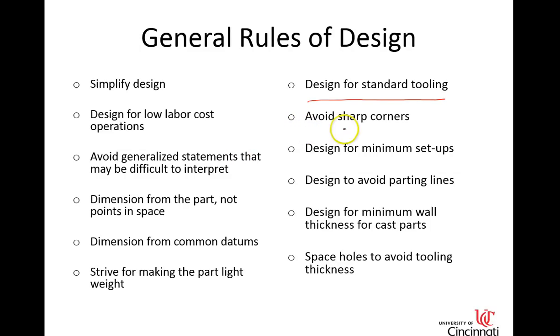Avoid sharp corners. Stress risers are one reason. Another one is they're not always that easy to manufacture. Design for minimum setups. Avoid parting lines if you're doing castings. So again, there's several of these in here. Those are some of the most obvious, the ones that jump out at me right away. And again, you'll have access to the slides.